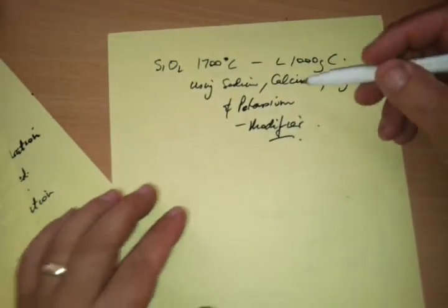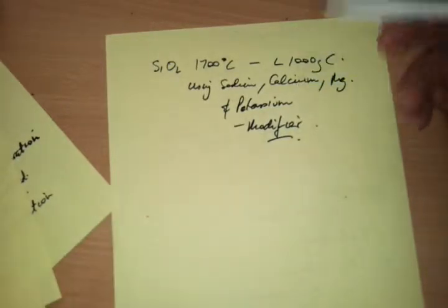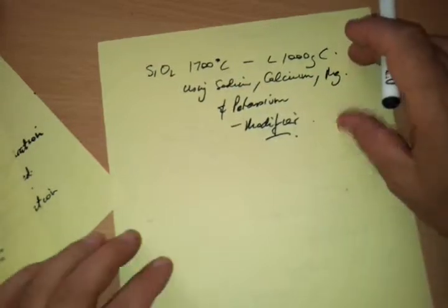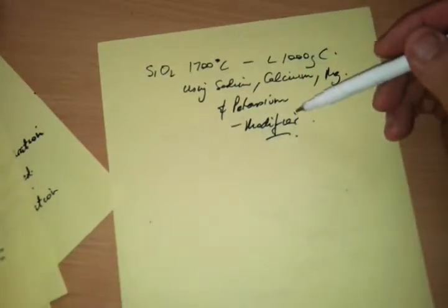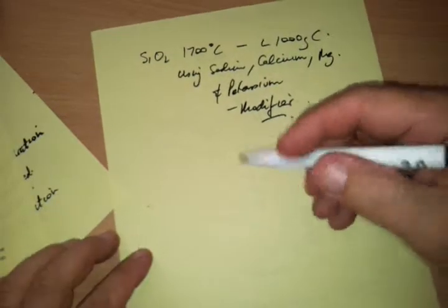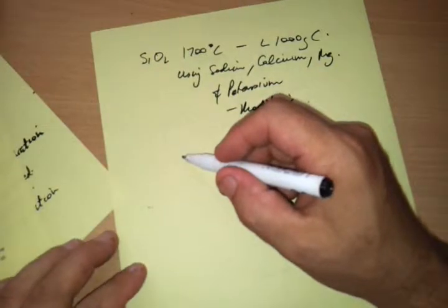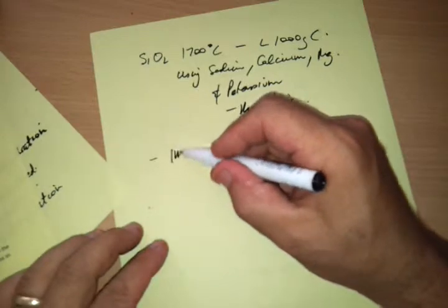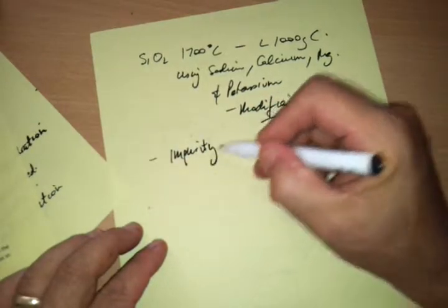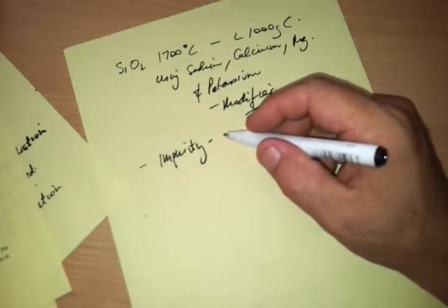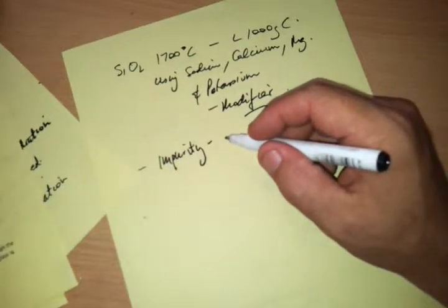Glass is usually melted together, so the silicon dioxide, which is the quartz or the cristobalite, is melted with modifiers and some recycled glass, which is called cullet, and it's then allowed to cool and solidify. The presence of impurities in the glass will usually be a locus point for crystalline growth. So an impurity inside the glass mixture will often be a seed point for crystals, and that creates a problem for us because it will create a weakness inside the glass and lowers the optical property of the glass, and that's not a good thing.